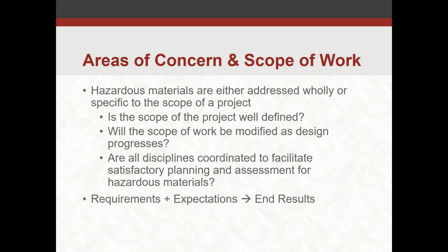Another critical thing is making sure all the disciplines are coordinated to facilitate a satisfactory plan and assessment for hazardous materials. A lot of times we work closely with an architect on their plans. There's electrical designers, mechanical designers, all the different trades. We want to make sure that a hazardous materials survey, assessment and design is going to cover their work as well. The last thing you want to do is get in the middle of a construction project and realize that the electrical scope wasn't appropriately accounted for on hazardous materials. Then you've got a whole slew of additional abatement that wasn't planned for and is going to cost a heck of a lot more.